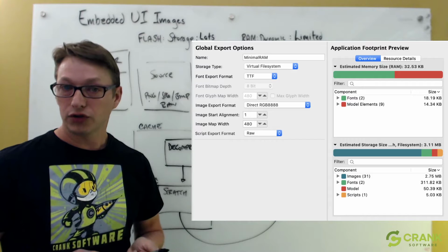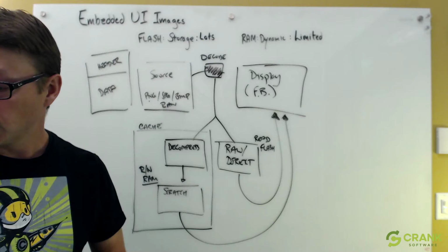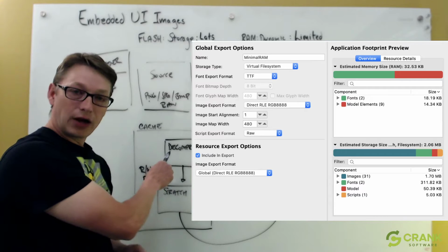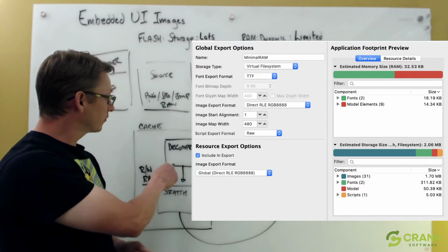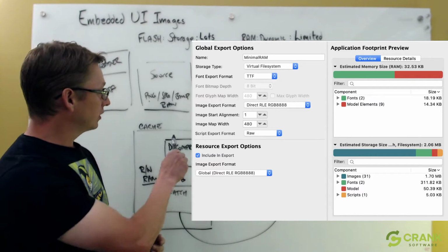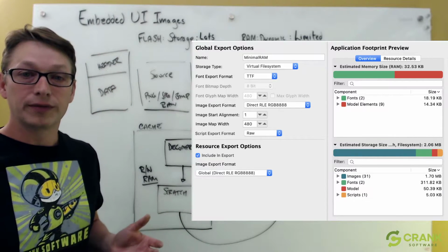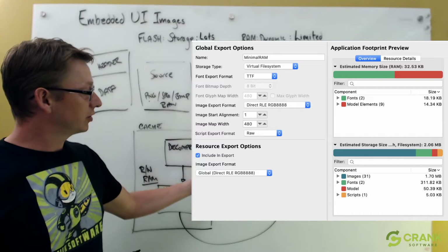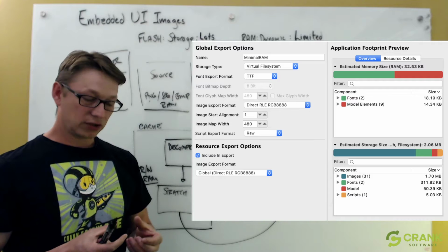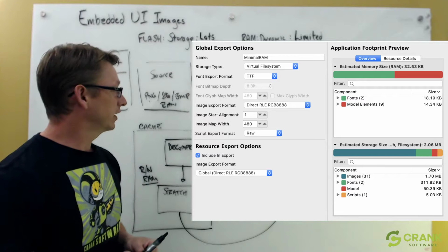Now, there are other choices that can be made here. If we wanted to further optimize this, we could look at a decode strategy that does allow us some level of compression, perhaps not as much compression as some of the more sophisticated compression algorithms, but gives us the ability to do a raw direct display. And so these are run length encodings. Run length encodings can be very efficiently implemented if you're doing direct draws, because really it's a pixel color followed by a count. And so you can do these runs of pixel colors very, very effectively.